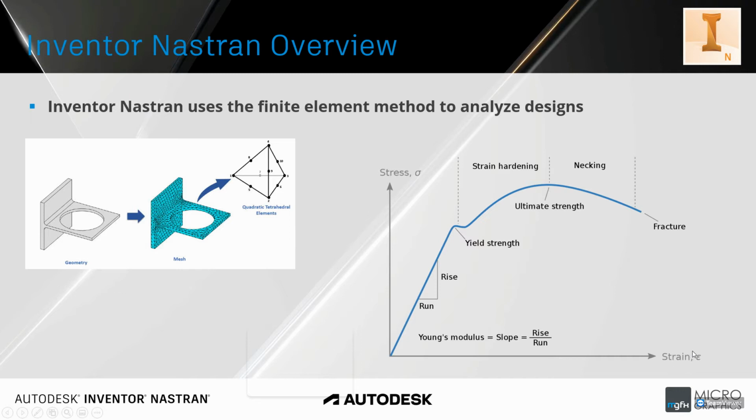Okay. On the other side, we have strain, which is basically the percentage change. So it's the change in the length over the original length of that steel rod. Okay. And why we need to analyze this is because you will notice that from the graph, in the first part, you will see that there will be a linear relationship between the two, meaning as you increase the stress, there's a linear change in the strain, right? But that only goes so far up until a certain point.